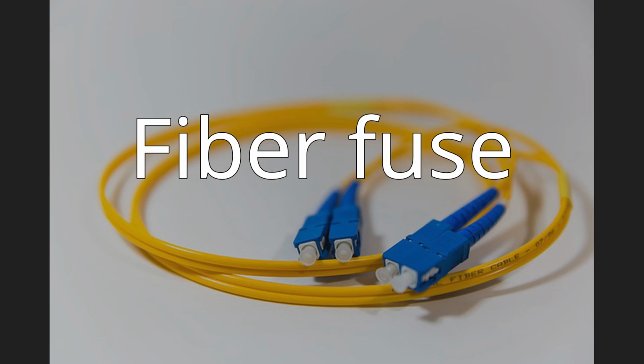Fiber fuse. At high optical intensities above 2 megawatts per square centimeter, when a fiber is subjected to a shock or is otherwise suddenly damaged, a fiber fuse can occur. The reflection from the damage vaporizes the fiber immediately before the break, and this new defect remains reflective so that the damage propagates back toward the transmitter at 13 meters per second, or 11 km/h (28 mph).